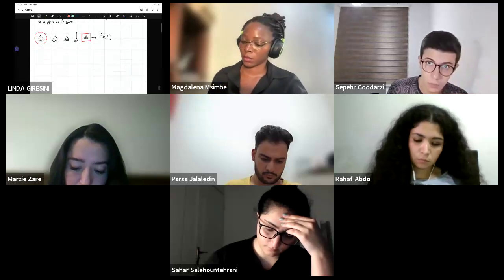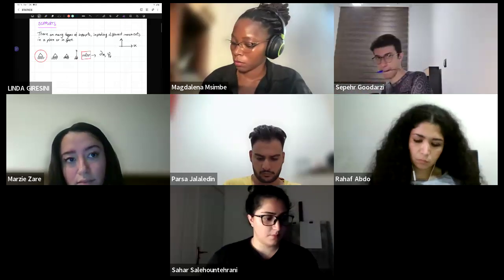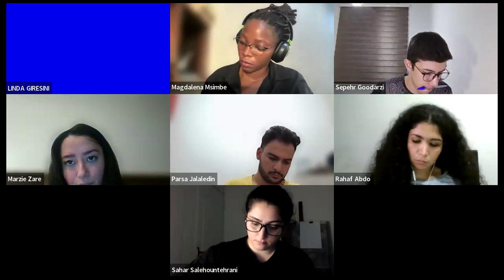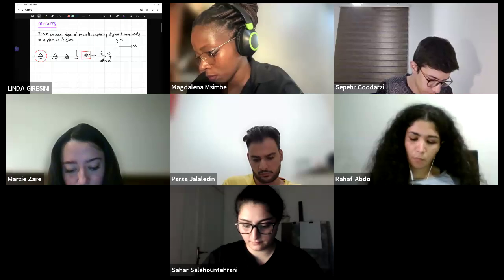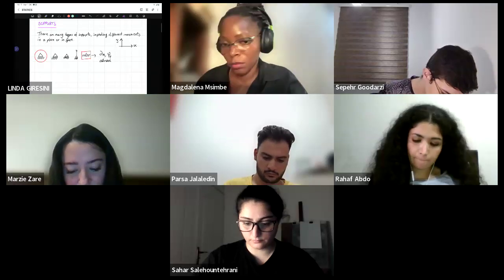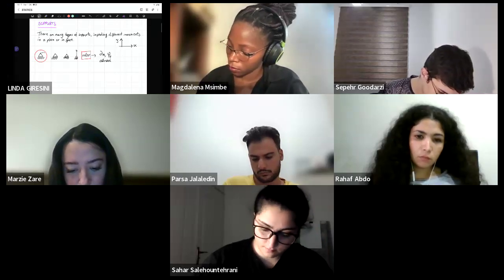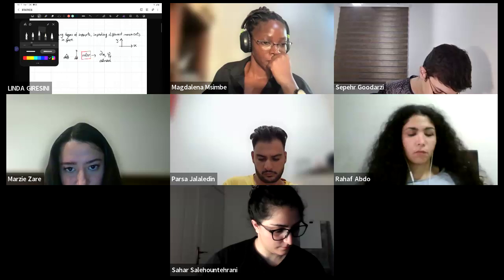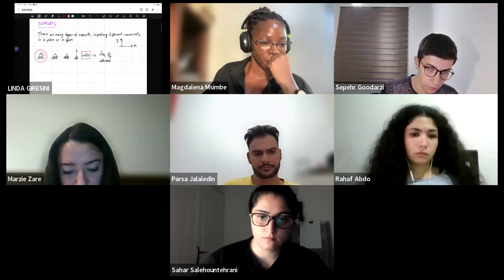What is delta x and phi z? Let me write this plane. The plane is x and y. So delta x and phi z allowed means that the node connected to this support can move in horizontal direction, or the extremity of the beam connected to it can rotate. For example, if a beam is connected, the axis of the beam can rotate, for example, like this. So it can rotate. Clear?